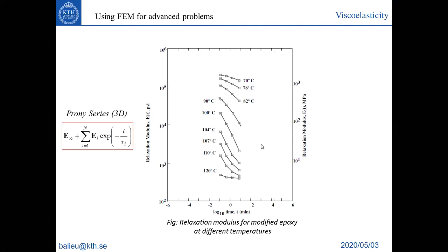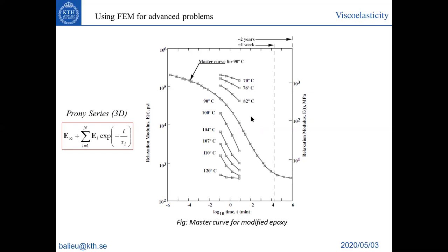For doing this, the aim is to compute something that we call a master curve. And for this, we will use the time-temperature superposition principle. The aim is, at one temperature, so let's plot this. Here I plot this master curve for 90 degrees. This is a complete curve at 90 degrees. And for plotting this curve, I only realize a horizontal shifting of the different curves.